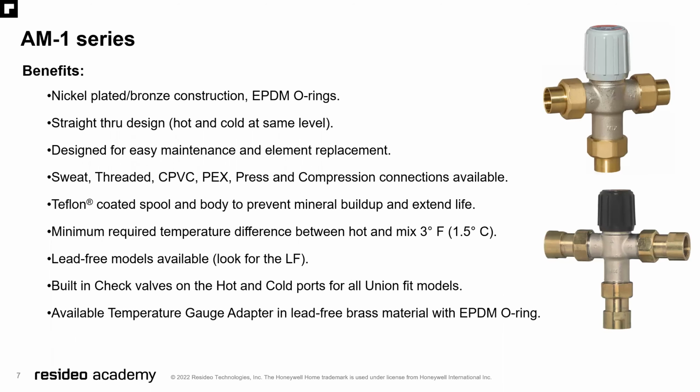The AM1 series: nickel-plated bronze construction with EPDM O-rings, straight through design, the hot and cold are at the same level, designed for easy maintenance and element replacement. They come in sweat, threaded, CPVC, PEX, press, and compression connections, with a Teflon-coated spool and body to help prevent mineral buildup and extend the life of the internal components. Minimum required temperature difference between the hot and mix is 3 degrees Fahrenheit.